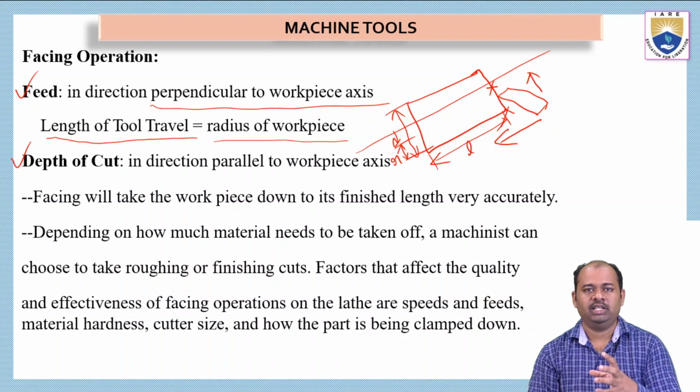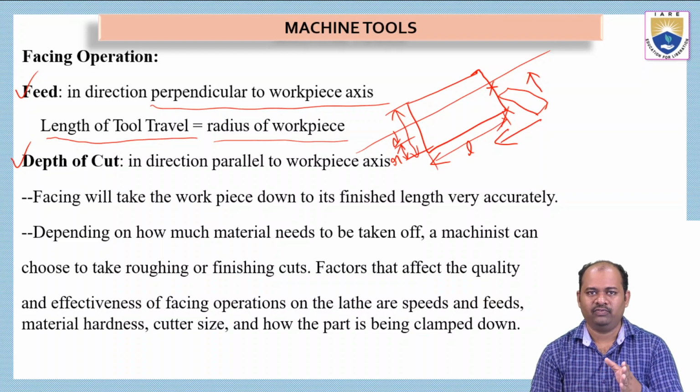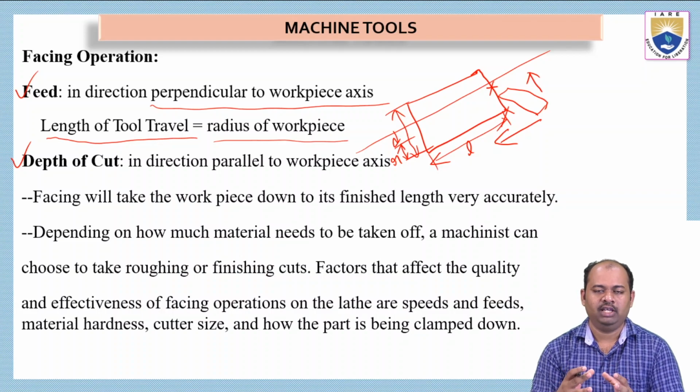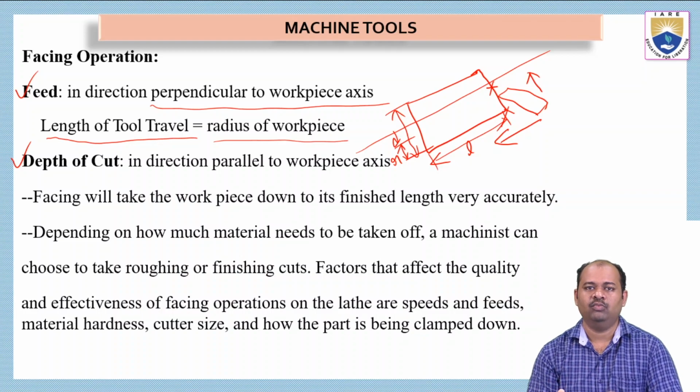But if we want to decrease more amount of material, we have to do it fast. We have to remove the material more initially, and then finally we have to keep some dimensional accuracy. Then we have to make only a little changes. Only small amount of material has to be removed slowly. Then we can get more smooth surface when compared to hard surface.